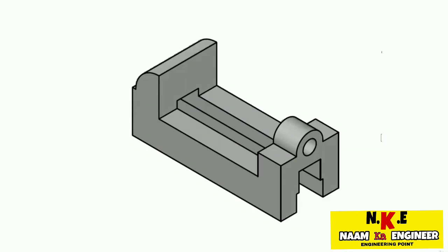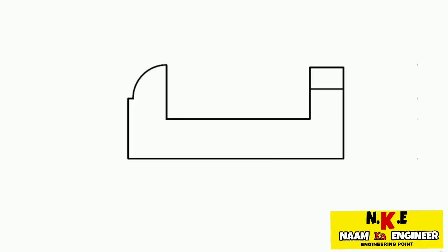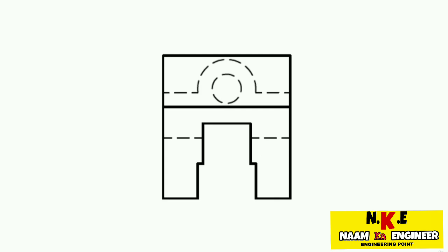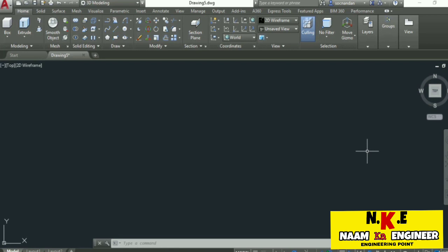In this video I'll make this simple 3D drawing, and this drawing is quite simple, which can be made in two different parts. So let's get started with the front view of this drawing. I'll start with the Polyline tool and select the polyline from the draw panel.